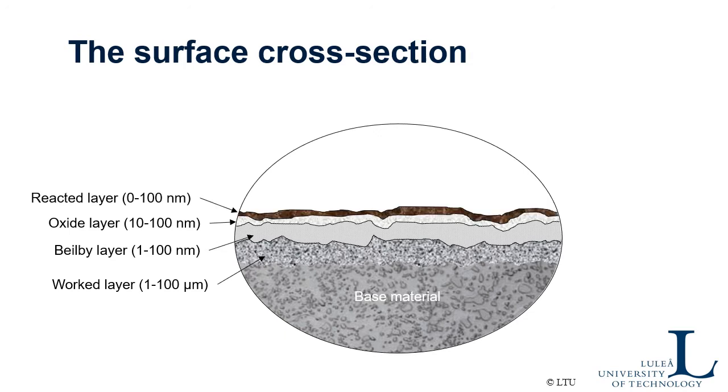And you may have some other reaction layer. In a lubricated contact, for example, you may react something with the lubricant. Parts of the lubricant, the additives, may react with the oxide layer and form an additional layer on top of that. And finally, you may have some physically adsorbed layer. It could be some greasy molecules sitting on the very top of the surface. And then you have the surrounding gas or fluid. So this picture is very good to keep in mind when we discuss wear processes.